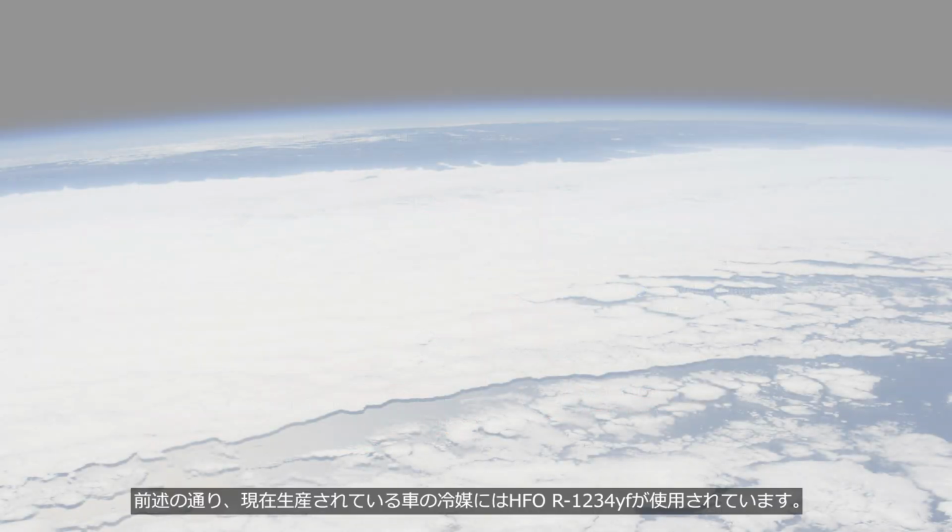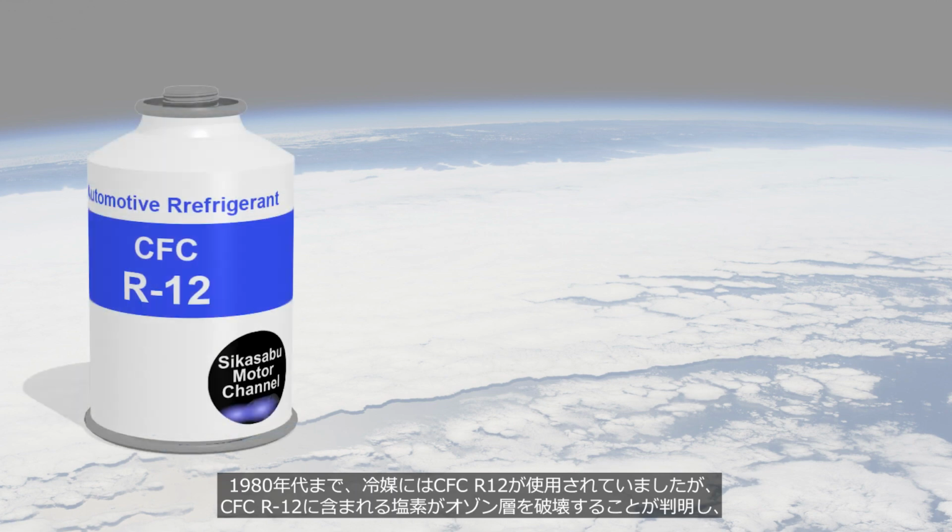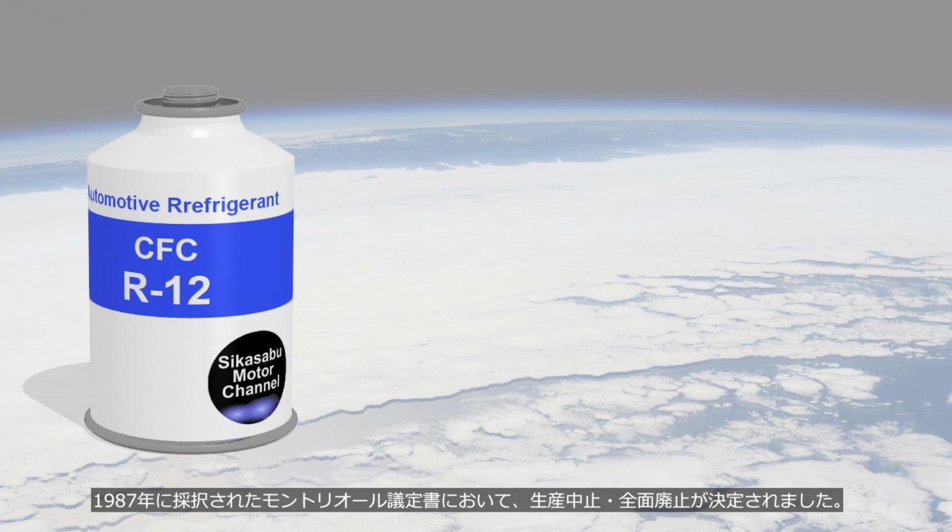As mentioned earlier, the refrigerant used in currently produced cars is HFO, R1234YF. Until the 1980s, CFC, R12 was used as a refrigerant, but it was discovered that the chlorine in CFC R12 was depleting the ozone layer. In 1987, the Montreal Protocol was adopted, leading to the decision to cease production and completely phase out CFC R12.